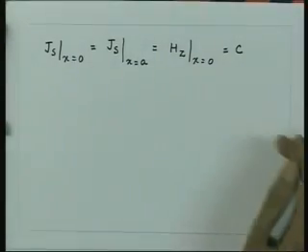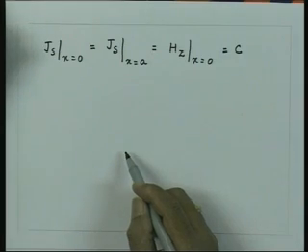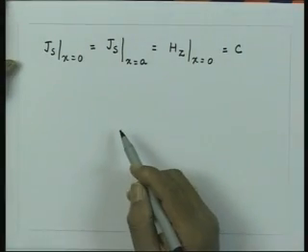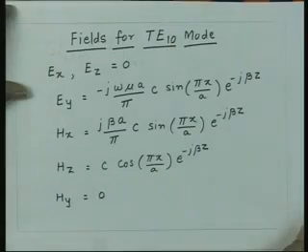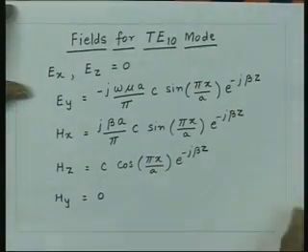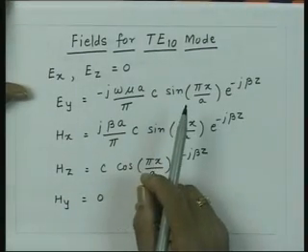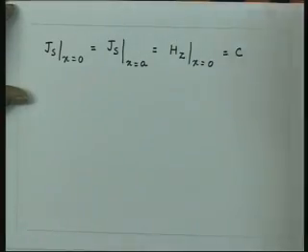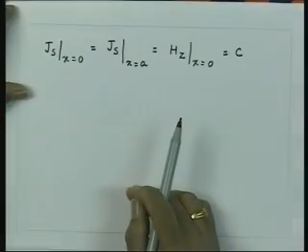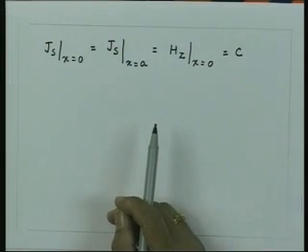From here then we can calculate the loss of the waveguide, but we have now the two components of the currents, one in this wall which is z oriented and the other one which will be x oriented. So in fact, we have to find the total current in this wall, which will be the vector sum of the two currents on the top surface and the bottom surface of the waveguide, and from there essentially I can calculate the total loss inside the waveguide.